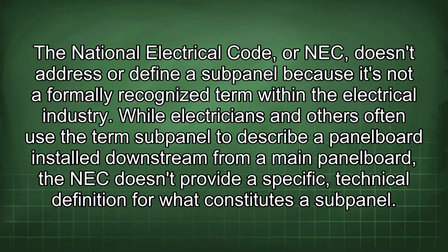The National Electrical Code, or NEC, doesn't address or define a subpanel because it's not a formally recognized term within the electrical industry. While electricians and others often use the term subpanel to describe a panelboard installed downstream from a main panel board, the NEC doesn't provide a specific technical definition for what constitutes a subpanel.